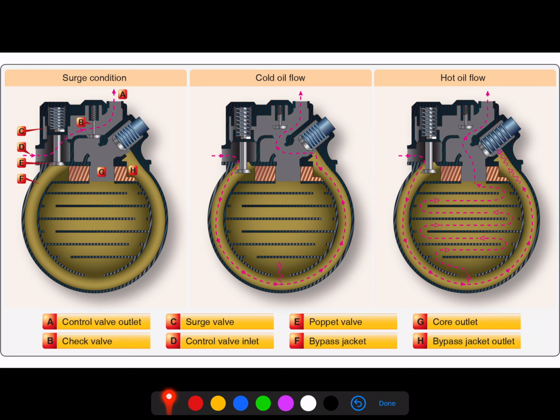One of the things that happens, and we understand this with how lubricants work, the colder a lubricant is, or the colder a fluid is, the more viscous it becomes, or the more resistant to flow. This has to do with the laws of states of matter. We know that as something gets colder, for instance water, it'll eventually start to increase in viscosity until it is frozen. We don't necessarily have to worry about freezing with oil, but we do have to worry about that relationship between temperature and viscosity. This is really the reason that we have temperature regulation to begin with. The reason for that is, as the oil starts to heat up, it becomes less viscous and becomes thinner.